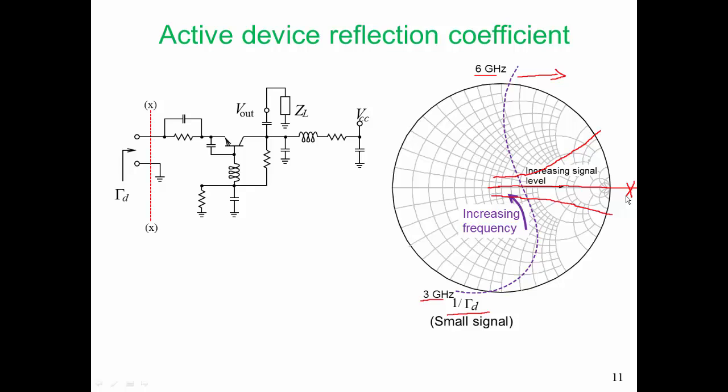So we're not able to stay on that horizontal line. So what we want is for the derivative of BD with respect to amplitude to be 0, and we have to follow these lines of constant susceptance, either that line or that line down there. And in future presentations we're going to talk about how we decide which of those we want to follow.